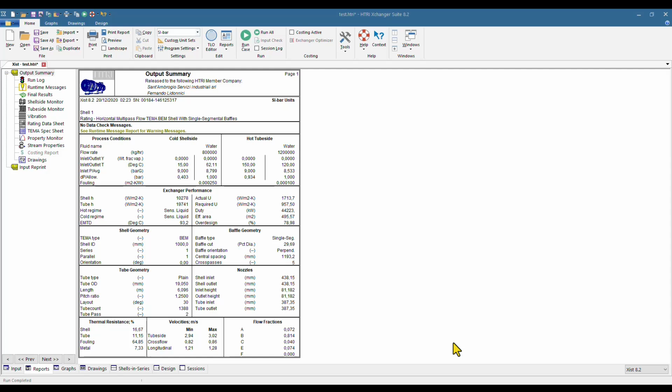Note, however, that generally speaking, the engineering companies do not like very much to have tube lengths which are shorter than the length they have specified. But generally speaking, if we reduce the length, cutting 1/2 of the standard tube length of 20 feet is generally acceptable.